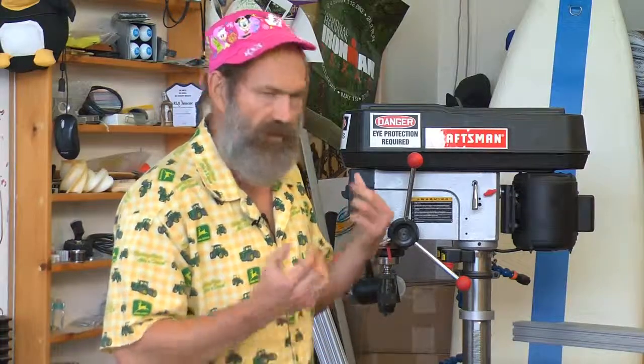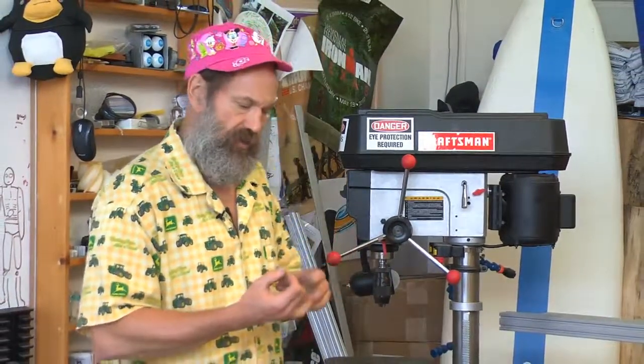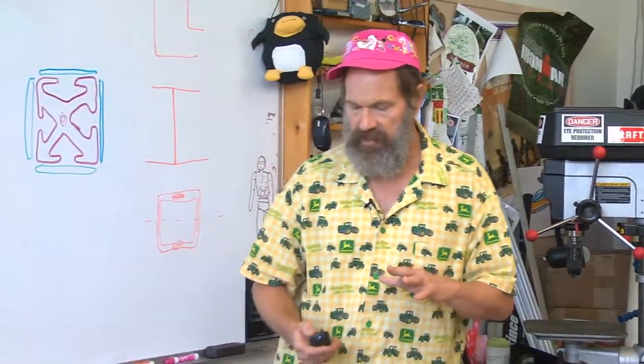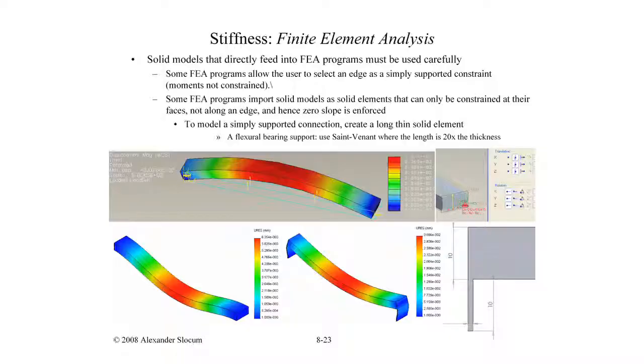So if I can write all that into one spreadsheet, I can very rapidly go through the stiffness of the gear, the strength of the gear, and play what if with different mods very, very quickly. In the end, check with your finite element analysis just to be sure. But remember, the name of the game is to be able to move quickly through your design.